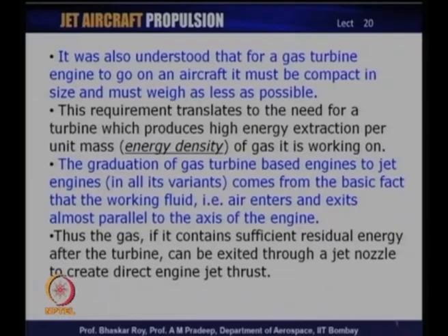Now, this requires, as we have discussed in the last slide, that the gas turbines which have to produce this high power would need to be fed with gas with very high kinetic energy. This kinetic energy has to be created, because the flow coming from the combustion chamber is indeed at very high potential energy of pressure and temperature, but it still does not have high kinetic energy. So, that is one thing that needs to be created.